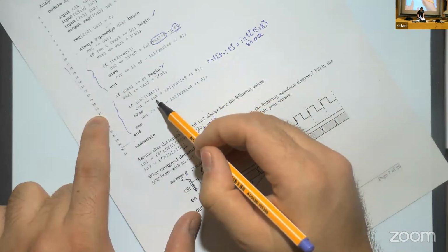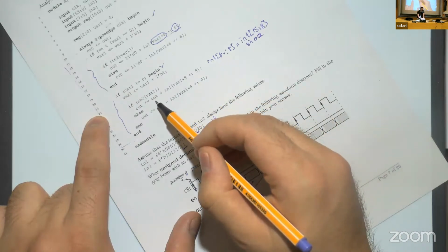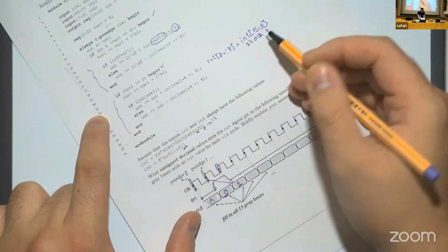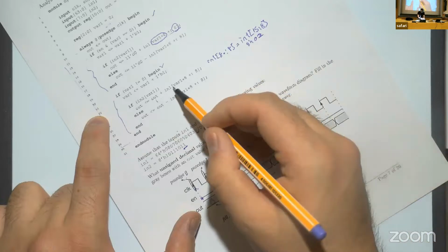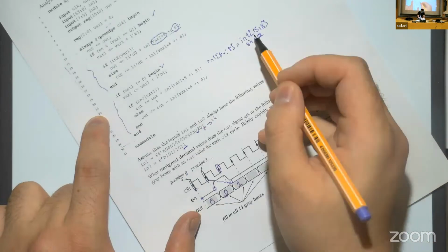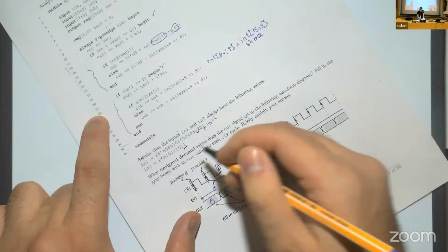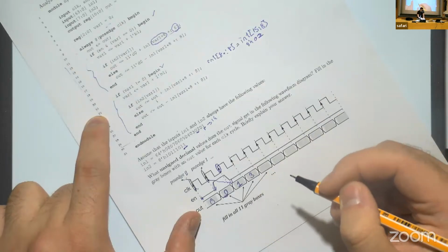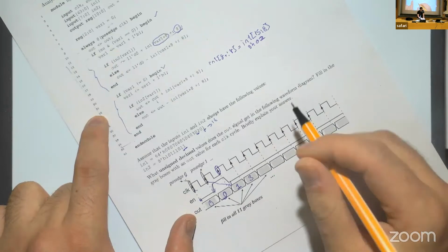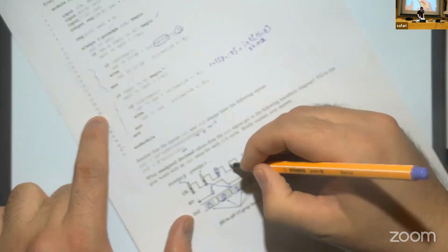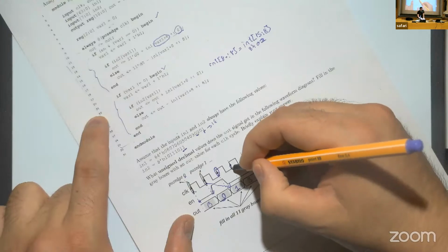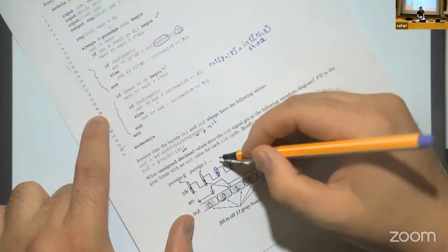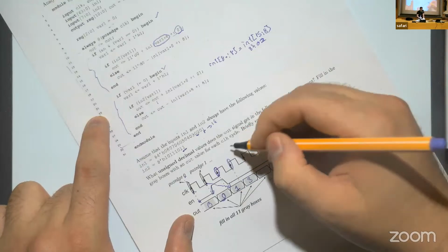The 4th bit is 1, and that means that we will perform addition. Out was 0, and the corresponding in1 is 4, which makes out 4. And then we execute again the fifth one. The in2 is 1 again, and what that means is out will be updated as 4 plus 5 here, which is equal to 9. And then we will execute again.